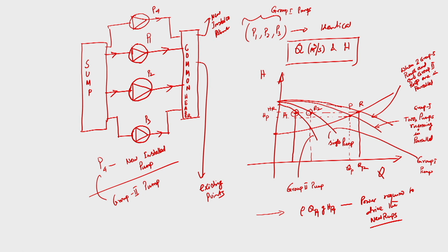So, what do we have to do? I do not know if QR is so high. Whenever a pump manufacturer supplies a pump, it is clearly written that the pump should be able to deliver from 25% to 125% of the discharge from its base design point.